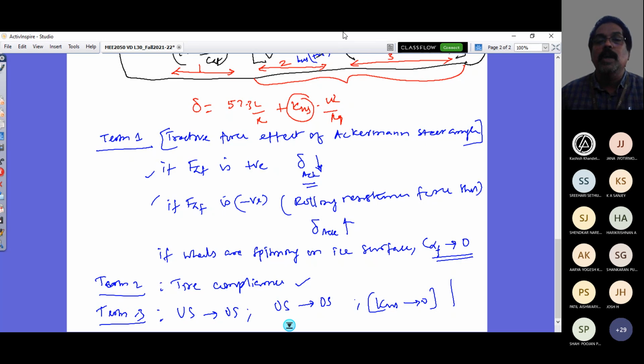So that is also going to contribute some influence on this understeer coefficient, and it will always get added to the understeer gradient. That's a positive value, right? And you also have the steering system and its compliance influence on the KUS. So these are all things; the formulas are given in the textbook. Please go through them. And here is where I stop our lecture.